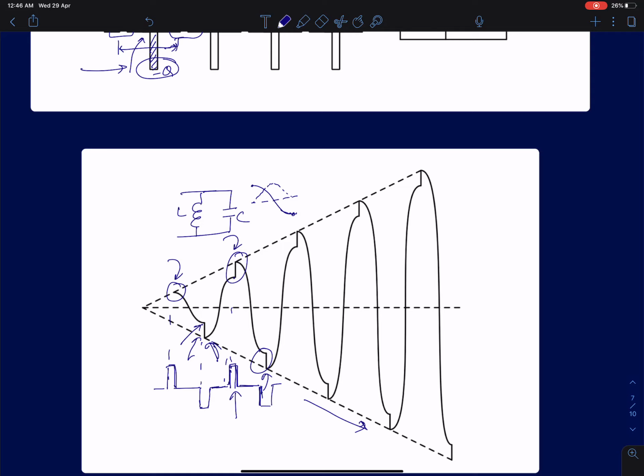If you recall, in the previous lecture I discussed that for an exponential function, the rate of change of the voltage is proportional to its instantaneous voltage, and then you will have an exponential envelope. But here the rate of change is always constant. You are injecting fixed packets, so in that case it's going to be a linear function. So dV by dt, this amplitude variation I'm talking about, is proportional to some constant. It's always constant, so your V will be some k times t. The amplitude is going to increase linearly. So this is a better approximation for a sinusoidal signal. If I feed a sine wave, this is the way your output is going to look.